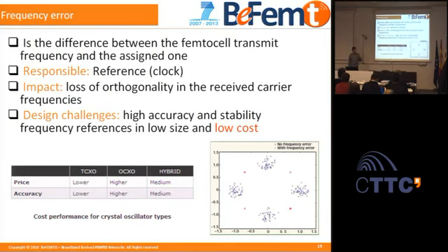And regarding the design challenges, to fulfill the requirements for LTE-Advanced, you have to use a high accuracy and stability reference. But it's a problem because these kinds of sources are very expensive. For example, if you use an oven controlled crystal oscillator, you can pay, for example, 1,000 euros, and that is out of scope here.